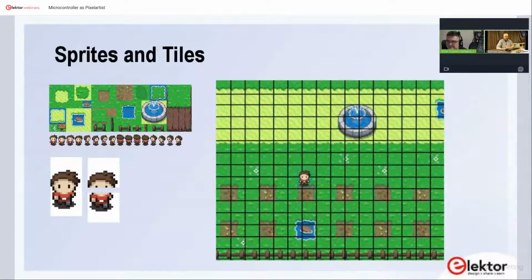For the DVI, with the Sprite library, it's quite easy to get started for digital video output. For Doom, as said, you need all the processing power even to get the VGA running. So there's no core to spare for the DVI output. That's sadly so, but you could couple two Raspberry Pi Picos, one just as the graphics engine and one for the rest of the logic. So nobody stops you from doing that.